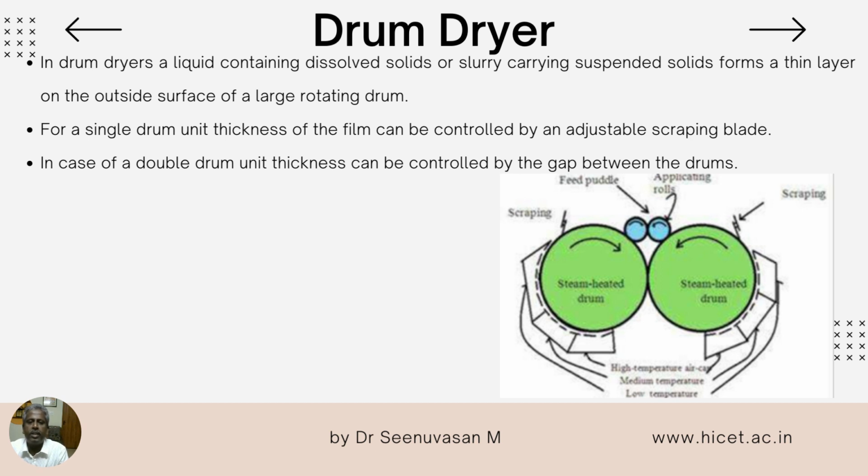This is a unit operation of this drum dryer when compared to the spray dryer or a rotary dryer. The solid collects on an apron in front of the knife and rolls to a container or to a screw conveyor. This carries the dried material out. The operation of the drum dryer is continuous, so that we are able to feed a huge amount of the feed and we can collect the dried product continuously.